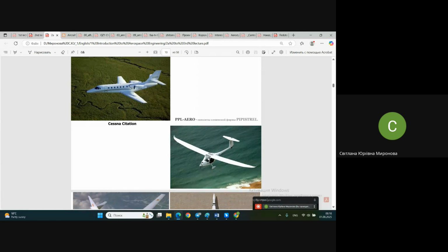And it's like a relative elongation of the wing. Usually in literature it's designated with the Greek letter lambda, little lambda, and this relative elongation, the longer the better in terms of drag. The longer the better because it minimizes drag.